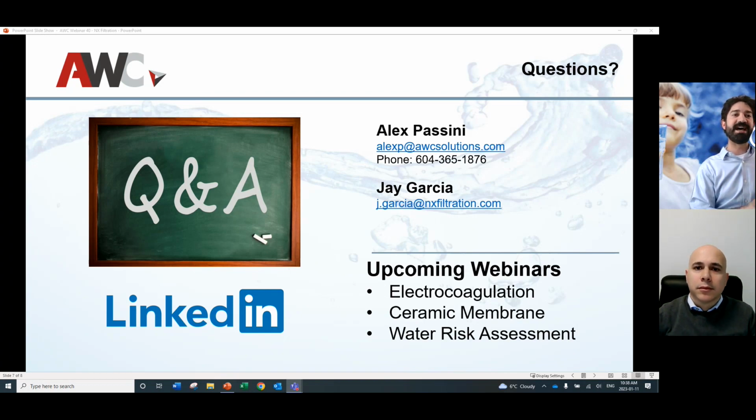Ours is inside out. A lot of the UF here in North America is outside in. Theirs is PVDF, ours is PES. The big thing, though, in terms of operation and cleaning protocol, is that we have crossflow. Generally speaking, a PVDF outside in will run in dead end mode. We have crossflow. That's one of the ways that we keep our membrane clean.